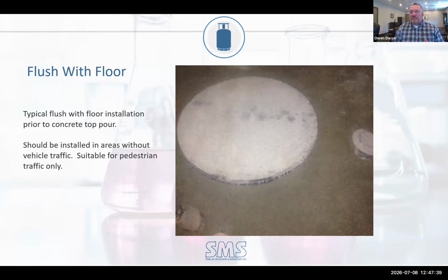but just think of it as a void space below. That plastic tank or neutralization tank is a void space. So you don't want it in high traffic. We often find them in facilities where they're in the loading dock area because that's easy for maintenance, easy for access. But again, make sure you put some steel bollards around that so there's no live traffic load.